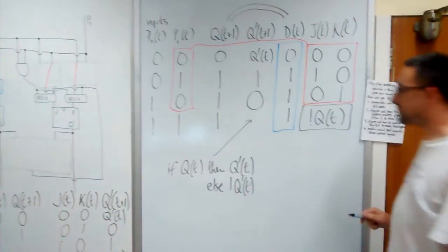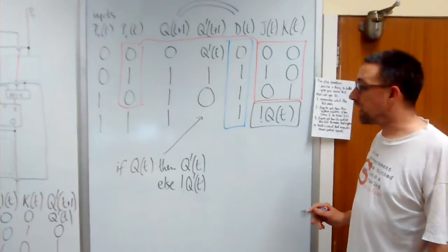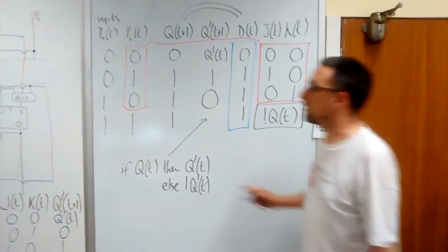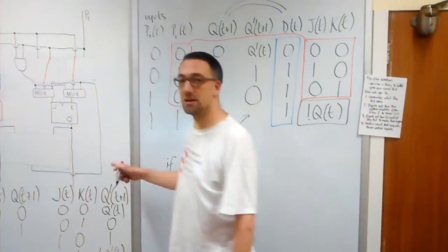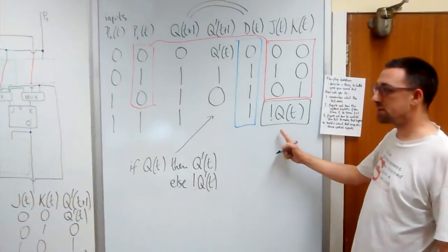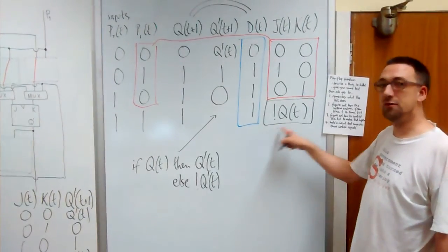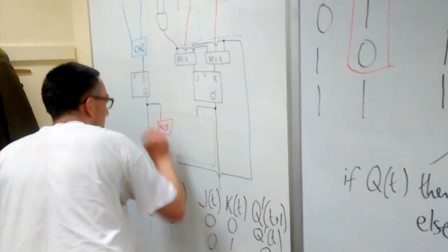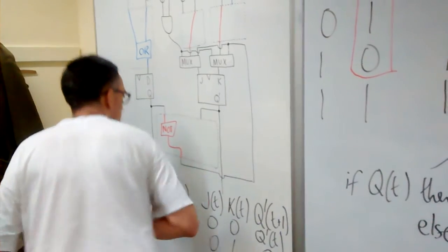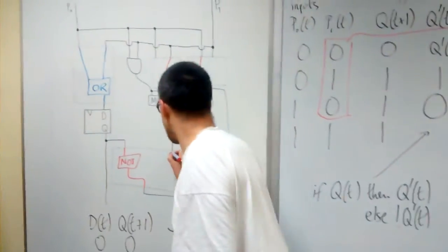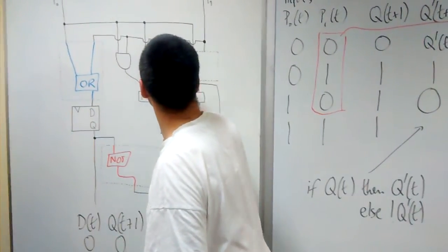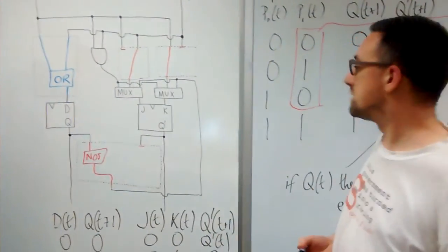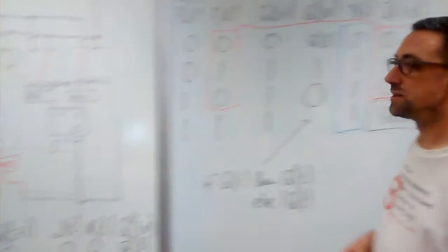And we can see that they're going to be equal. They have to be equal because the wiring doesn't give us any other choice, but fortunately for us, they are equal, and they're equal to the negation of Q of t. So all we have to do is put a NOT gate in between Q of t and the output of that circuit. So the other wires are just ignored, and we've completed the logic.